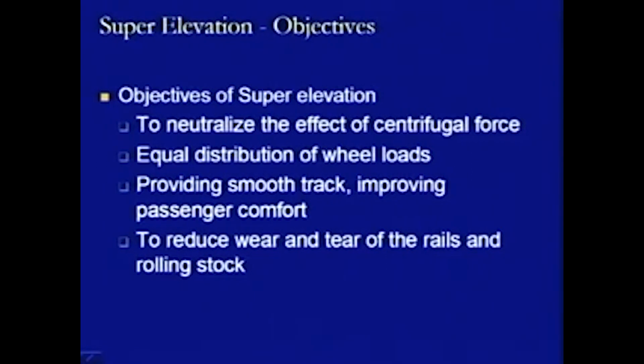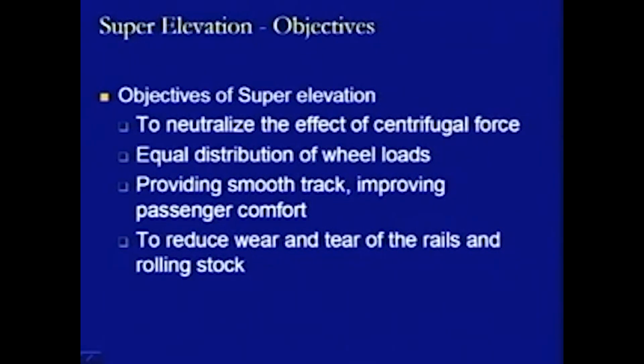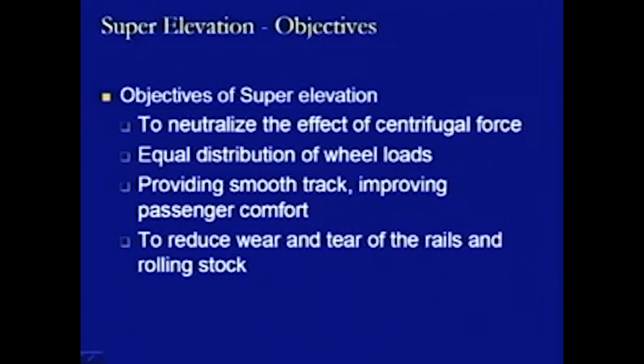Further, without the provision of super elevation, the centrifugal force acts in the outward direction, and because of the movement of the overall rolling stock outward, and because of its rigidity, the relative movement of the front wheels and the trailing wheels means there are all chances of wear and tear taking place at a higher level.